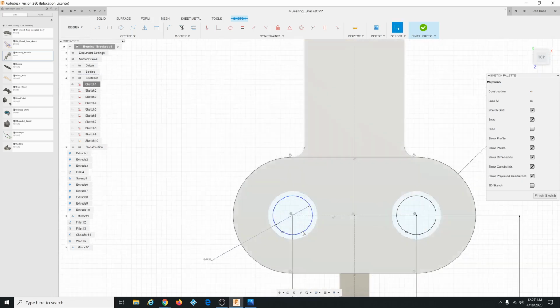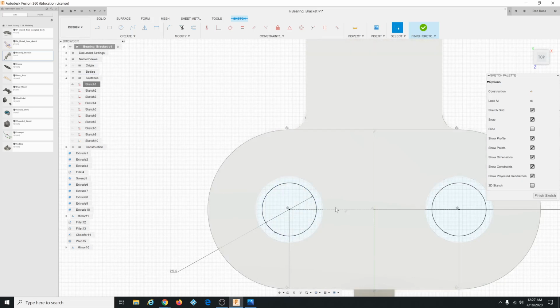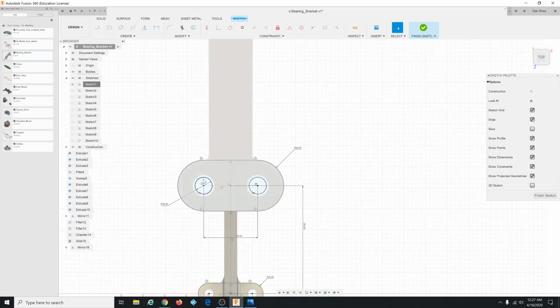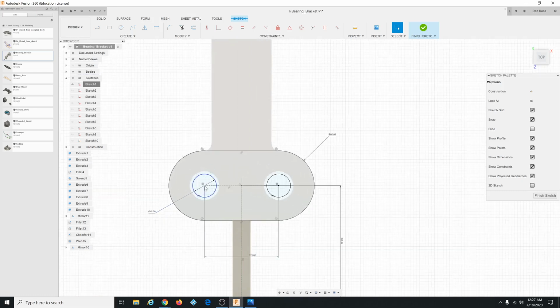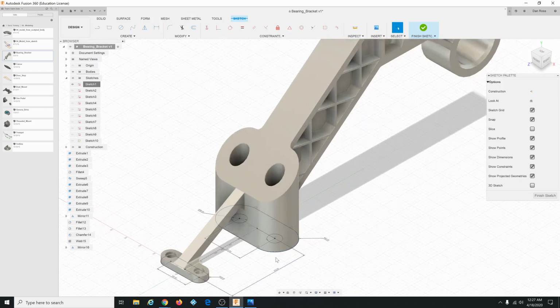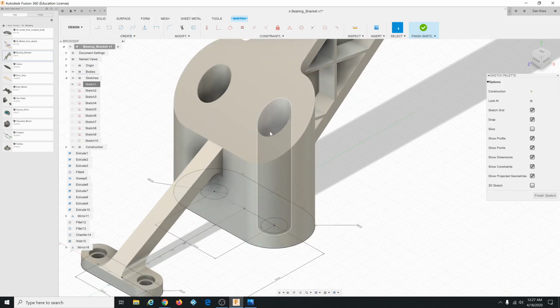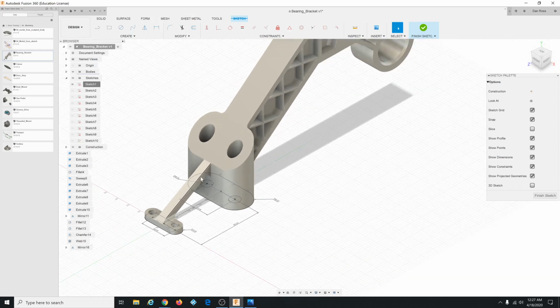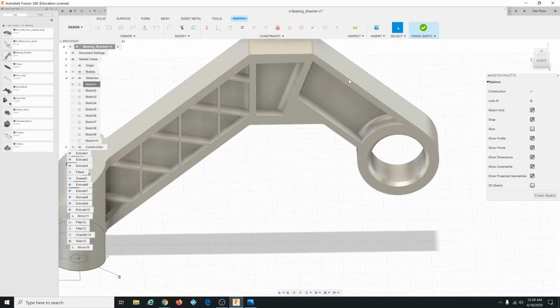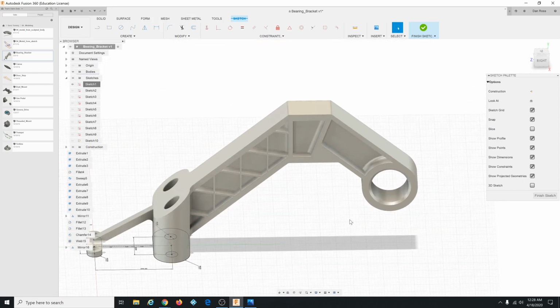Okay, the hole got smaller, see the hole, but not the geometry built from the hole. Right? The hole on the sketch got smaller, but the extrusion made from that hole did not get smaller. So we've sort of broken the parametric design thing, but we were able to perhaps make a change that we might not have been able to make, theoretically speaking.